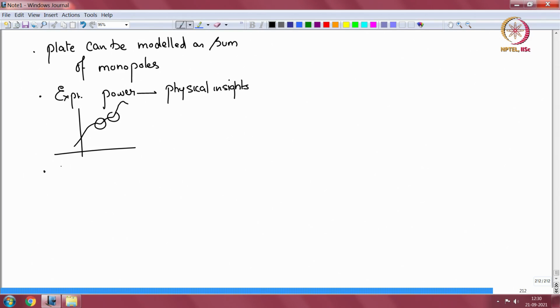We followed this by sound transmission. Initially a rigid infinite partition mounted on springs and dampers, then an infinite flexible panel with a plane wave incident at an angle.